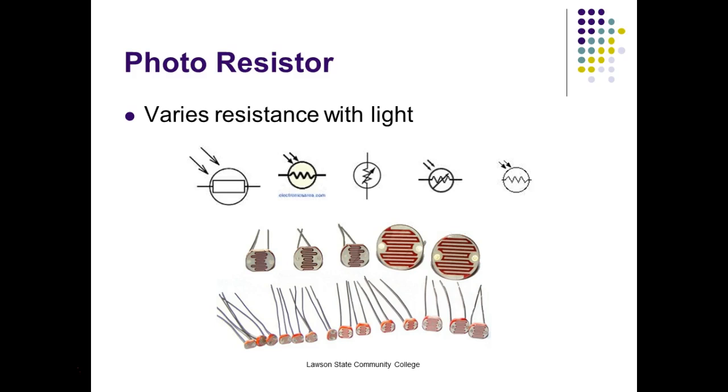But now they use what? Now just about all the lights, even around here, use a photoresistor. And they're pointing up at the sky. And so now we don't have to use a timer anymore, because at a certain darkness, it turns the lights on, and at a certain brightness, it turns the lights off, right? So even now, if a bad thunderstorm comes on, I've got a street light on the pole right out by my house, and I've seen it come on during the daylight. It's just set to come on when it gets so dark out there, right? So it's pretty neat.